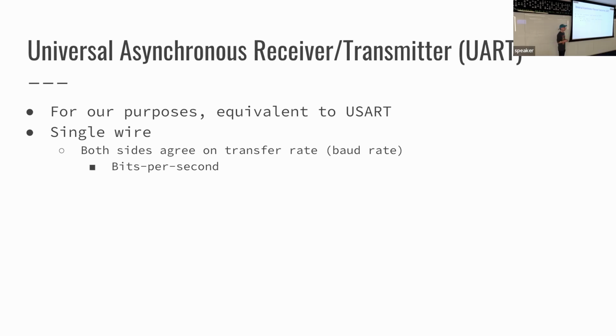You'll often see UART used early on in a project for sending ASCII characters. And if you set the wrong baud rate, then you've got your terminal connected reading the UART signal from your board, trying to read whatever your printf is outputting, and you'll get garbage if you have the wrong baud rate. And that's a very common thing when you're setting that up.